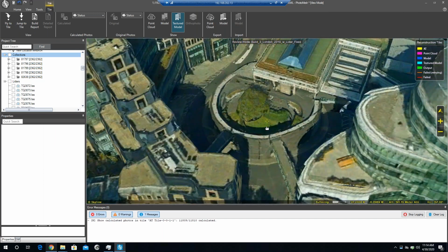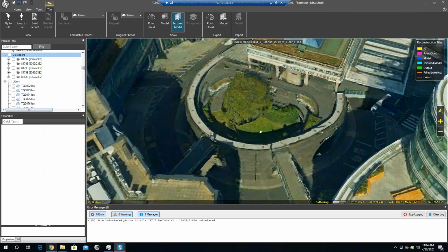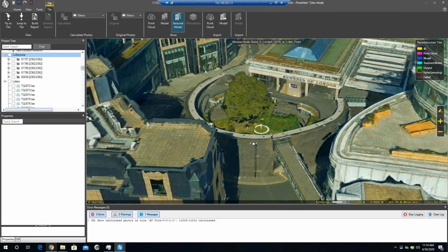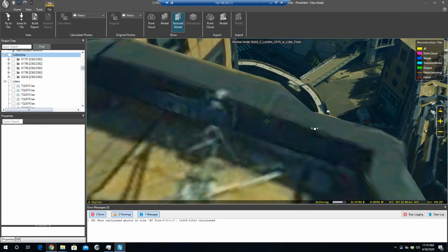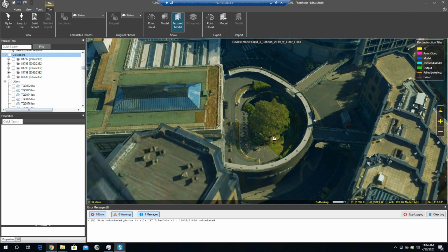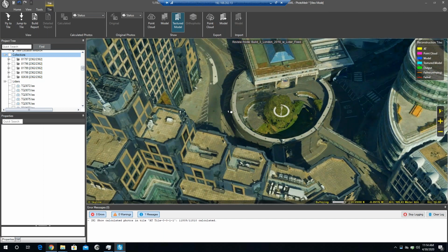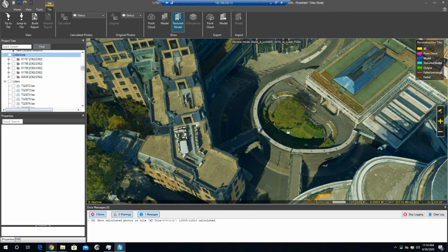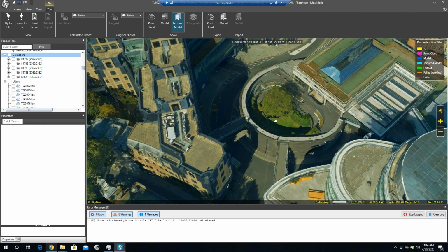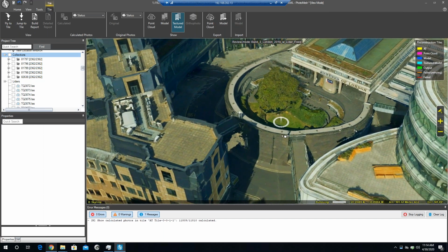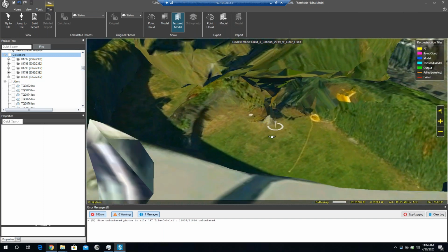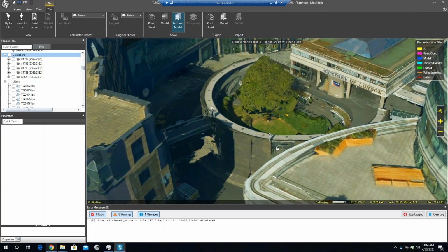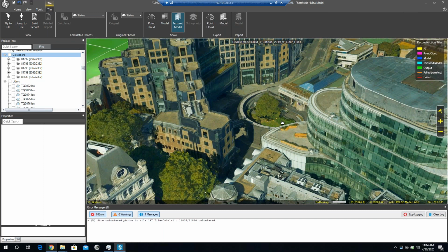And over here we can see some of the ability of the images to still texture the area underneath the tree. So it's a combination of the LiDAR geometry and the texture from the images, which might not have been able to correlate a point, but we calculate the normals from the images and we're able to then bring in texture into this area very tight under the tree. We also do very smart interpolation.